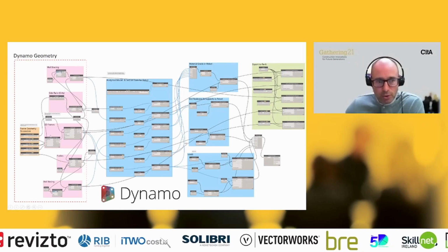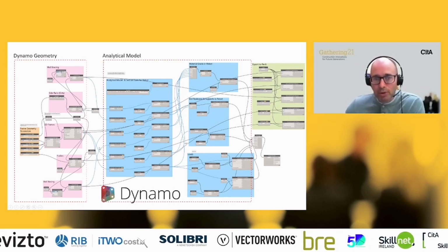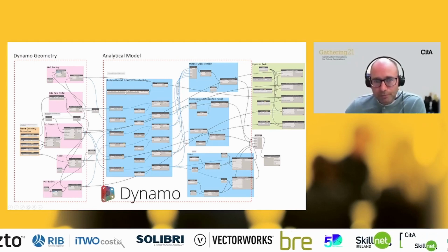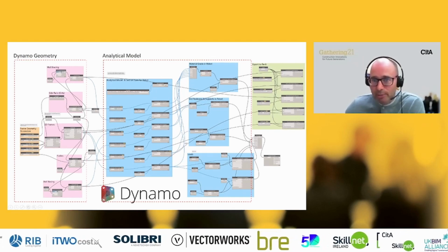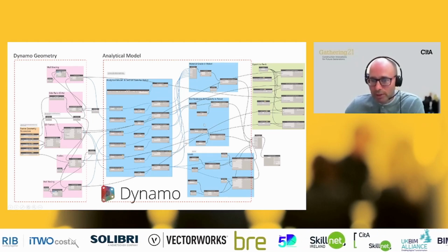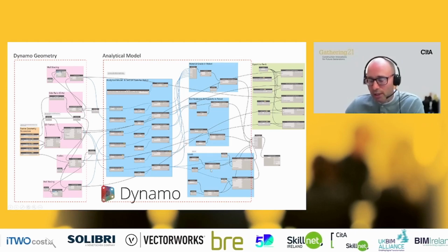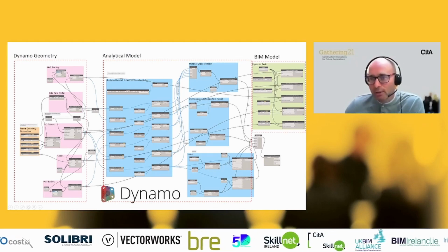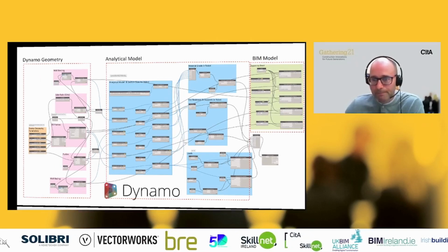So we have all of these different nodes coming from the structural design package, which create that portal frame geometry. Once that portal frame geometry is created, we have a structural analysis package, as it's known, which can be downloaded within Dynamo. This is where we can define analytical properties such as the material grade for Robot, certain end releases or supports that would be within Robot, and even loads or load combinations. So you're defining everything within Dynamo. You're not having to define it in another platform. And then finally, the last bit of our script is how we would export our BIM model into Revit.